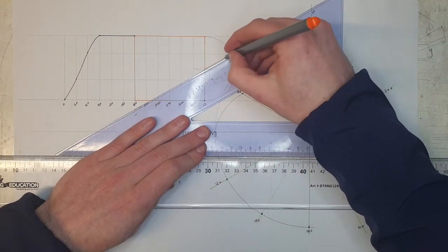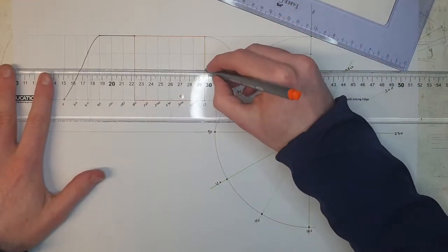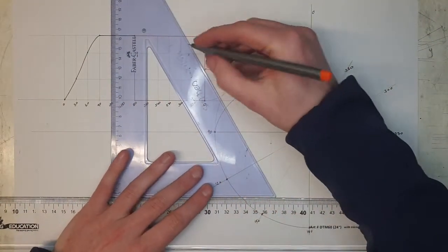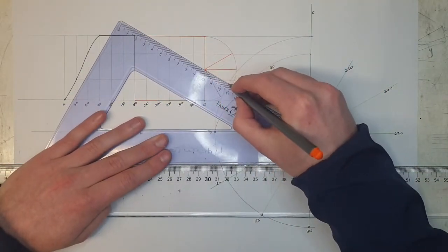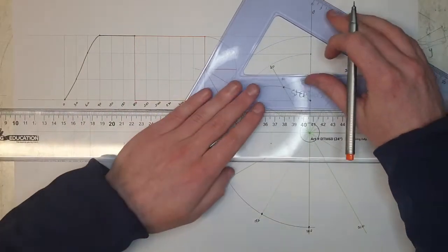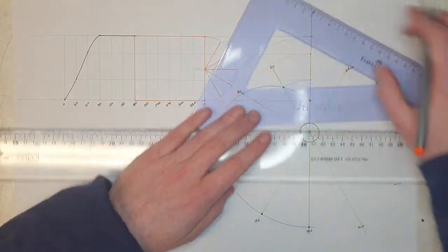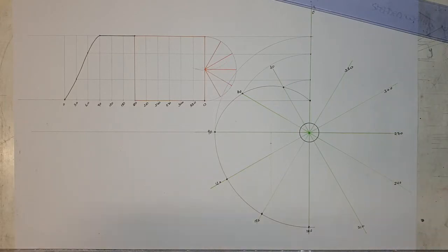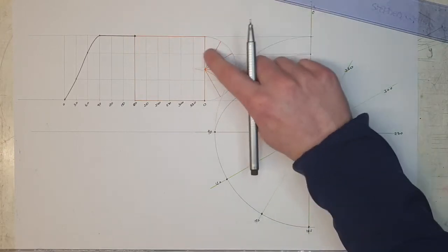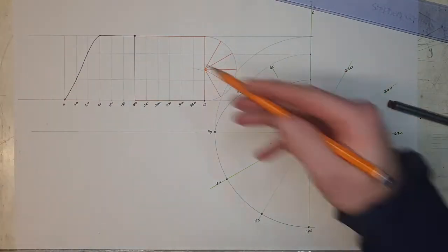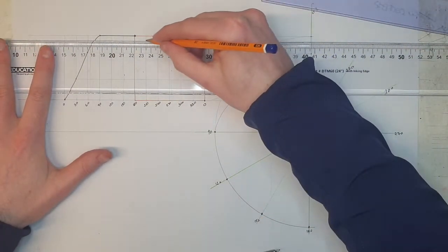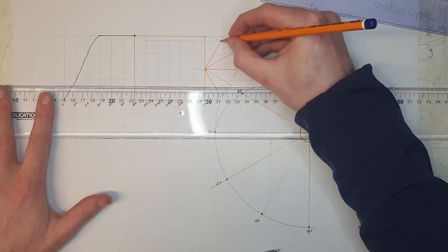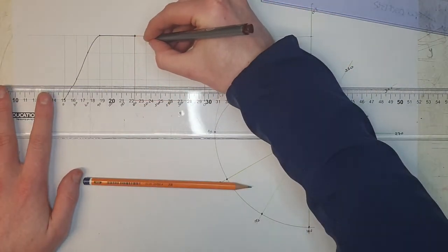You then divide that semicircle into 6 parts. So start point is here. The next point is going to be along this next line here on the 210 line. What I'm going to do is bring the next point across from the circle, should I say. So this point comes across and we end up with a point here.